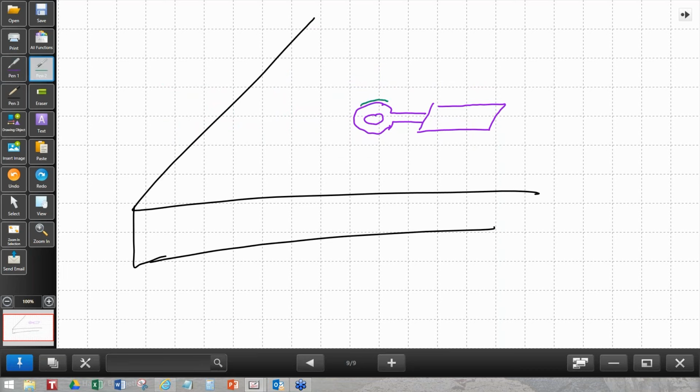And the solder mask now kind of goes around like this, okay? So there's an opening in the solder mask where an open via exists, and the solder from here is wicking and going down the hole.